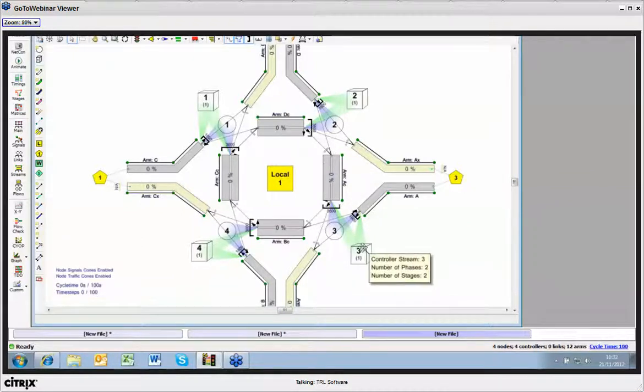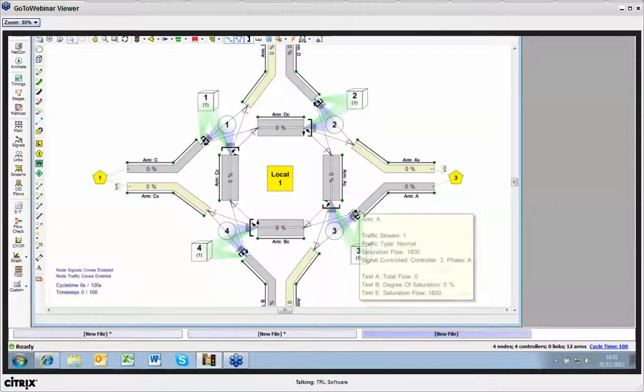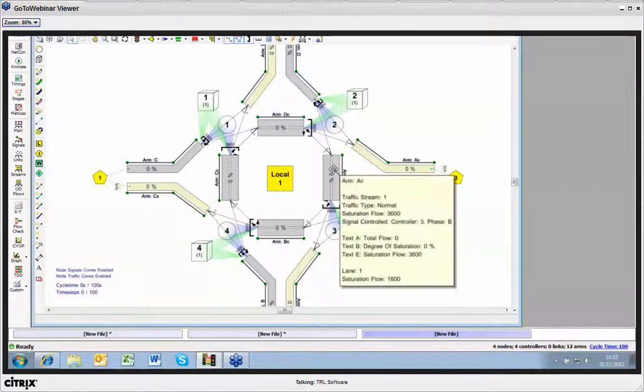So the kind of things we're interested in looking at, we've got 3 different traffic models in Transyt. We've got the traditional platoon dispersion model, which any users of earlier versions of Transyt will understand and be happy with. We've also got the CTM model, which stands for the cell transmission model. What that does is it doesn't model the dispersion of a traffic platoon from one stop line to the next. It models closely spaced stop lines. So specifically, CTM has a real application at a signal controlled roundabout like this for your circulating carriageway.